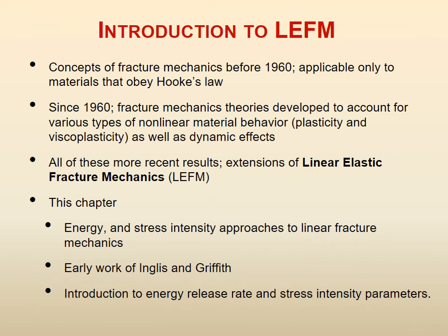Concepts of fracture mechanics before 1960. Before 1960, right? It had started. They were applicable only to materials that obey Hooke's law. You remember Hooke's law is force is directly proportional to deformation. So F is equal to Kx, where K is the spring constant or the elasticity and so on. So materials which obey this, of course materials that obey Hooke's law are all the metals and so on in the elastic range.